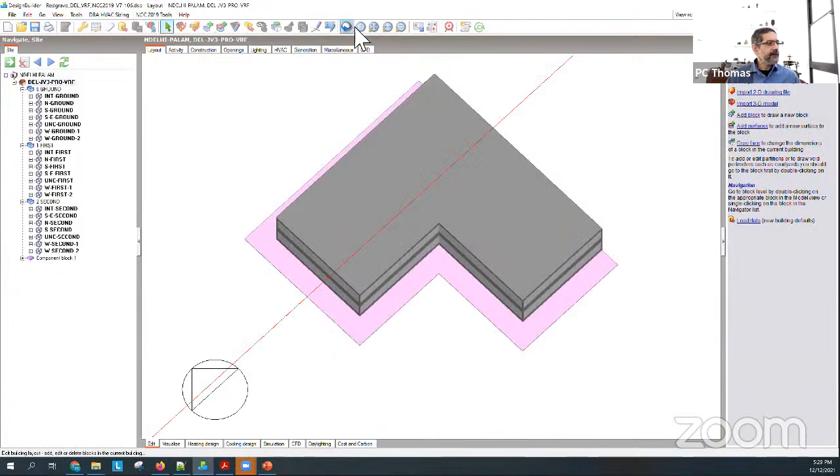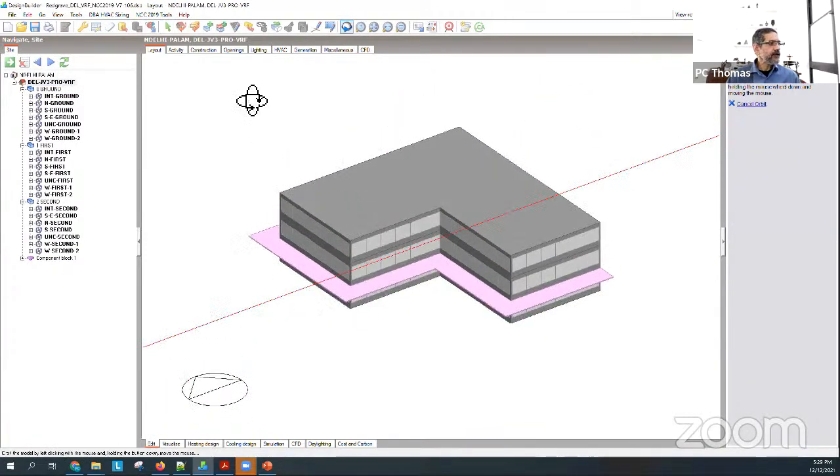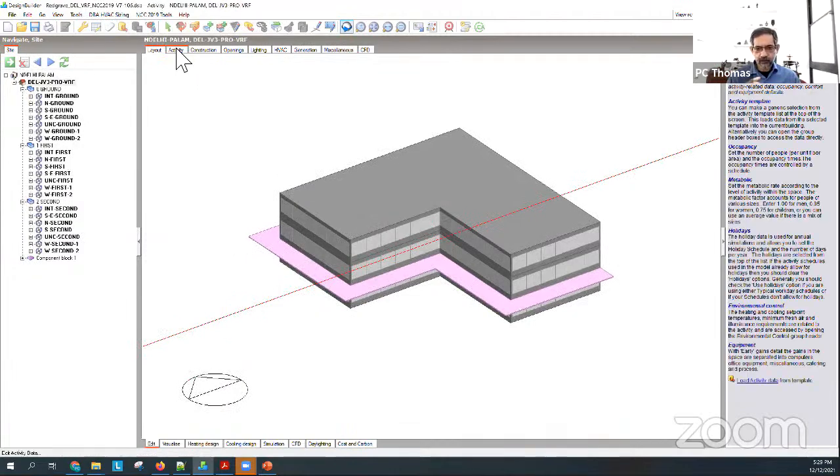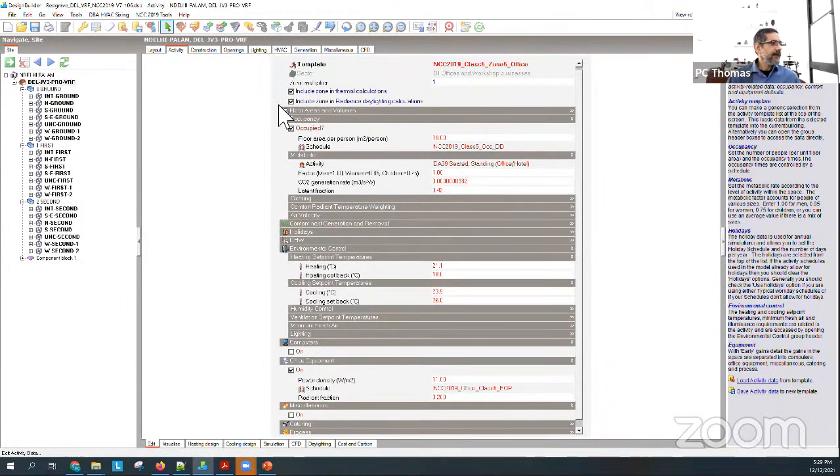So here's my building. We've adjusted all those internal zones, the internal loads, beg your pardon. We've put some thermostat settings. So here I put 21.1 for heating. We're not going to be that interested in that. We're really interested in the cooling thermostat, and that's 23.9. Now, you may want to change that, okay? And that's okay. So if you decide that in India, you're okay with having 26 degrees, fine. You can change the number, okay?